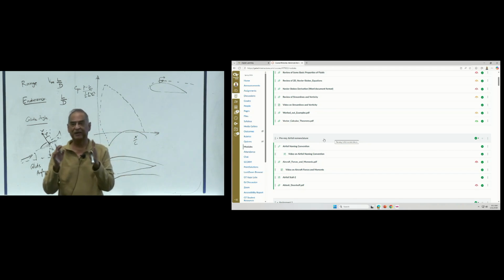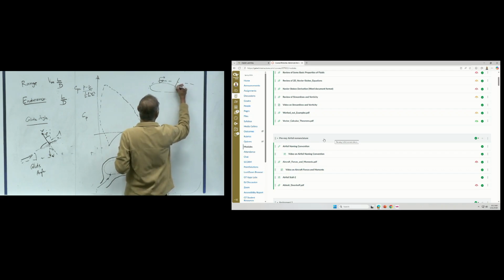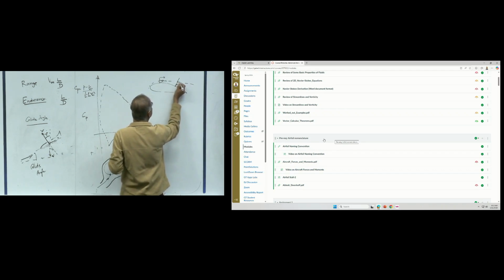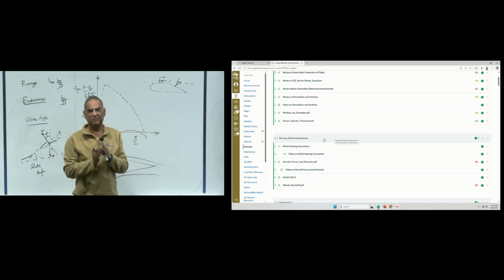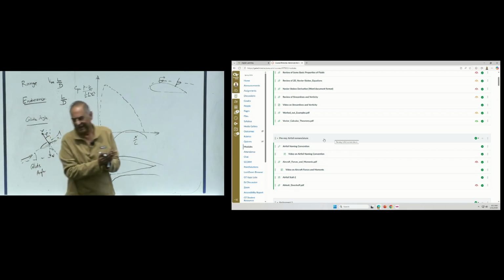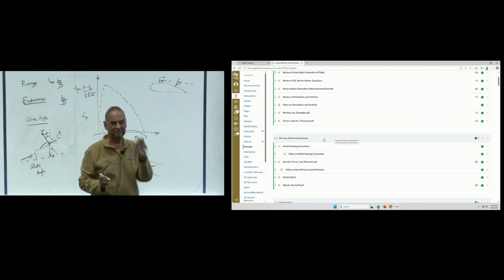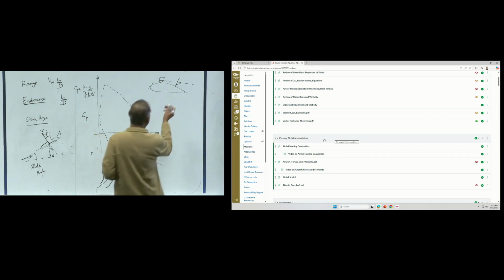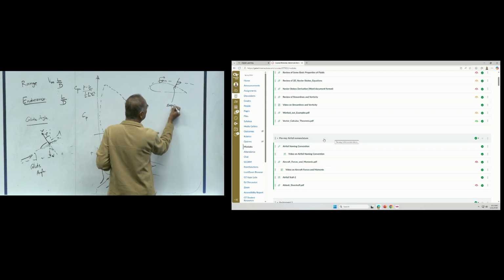So depending on the airfoil design, sometimes along in here, the bottom layer of the boundary layer will become a zero velocity gradient. So the particles are standing there, they neither move forward nor backward, they come to a dead stop. That's called a separation point.